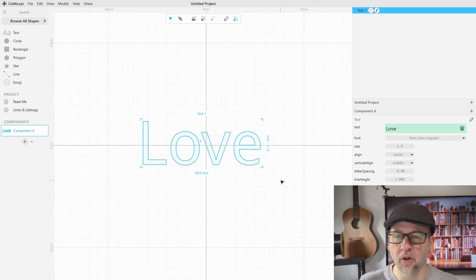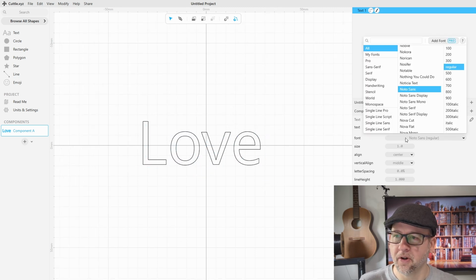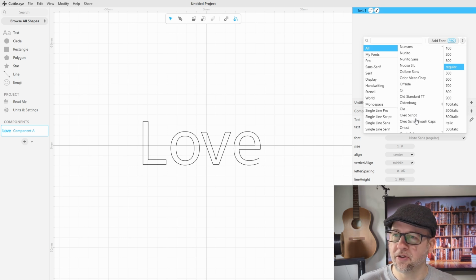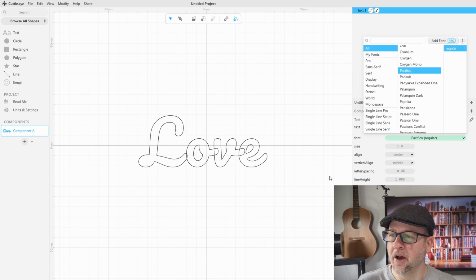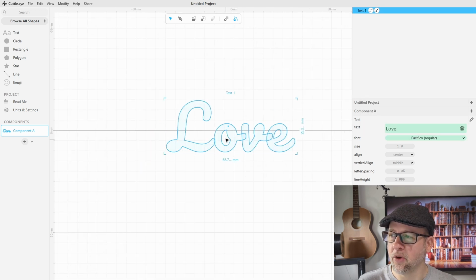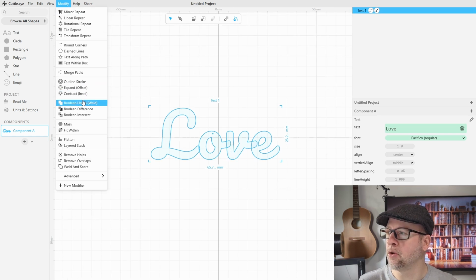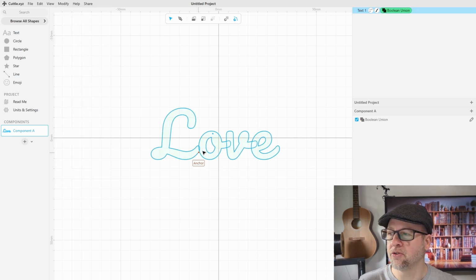So now we're going to go with a script, a cursive style text. So let's go to, what is it, Pacifico? That's a good one right here, and we'll click there. Now we can see that some of these are overlapping each other. To get rid of that, we're going to go over here to modify, and we're going to go to Boolean union weld. So it's going to get rid of those. All right, so now we just got rid of those, and it's all one piece now.